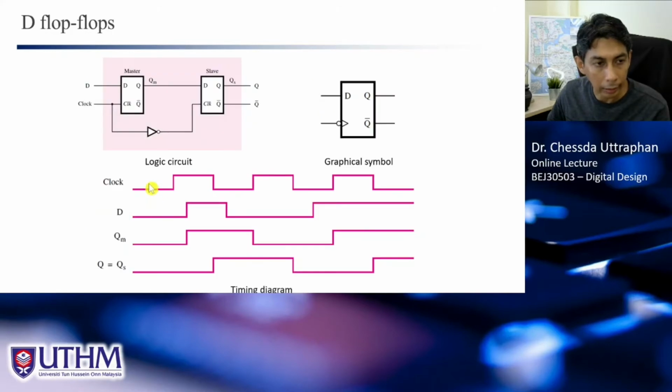So that is latch, and this is flip-flops, where the output is sensitive to the clock edge, whether it is positive edge triggered or negative edge triggered. In this case, it is the negative edge triggered. So the output will follow the input whenever there is a clock edge here, whenever the clock changes from 1 to 0. Here we can see that we have 0 go to 1 because here D is equal to 1. Right? So this is negative edge triggered. So remember, flip-flops are sensitive to the edge only, but the latch is sensitive to the level of the clock.